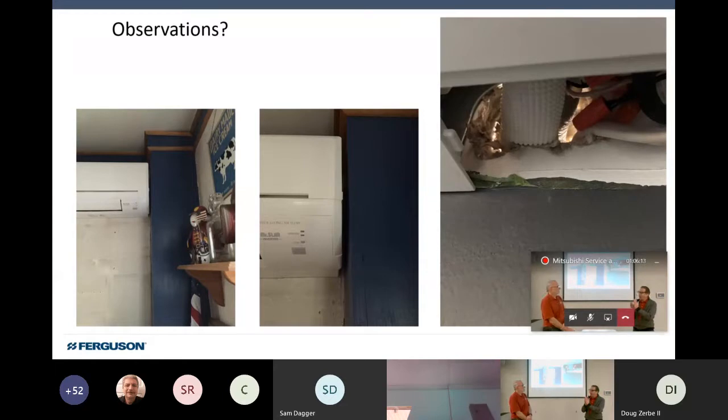What we found out was that we were not picking up enough return air through the unit to be able to truly get a good sensing and a good operation. And we'll explain why very shortly. That was the main thing: our return air sensor is on that side and we blocked the airflow that should have gone over that.